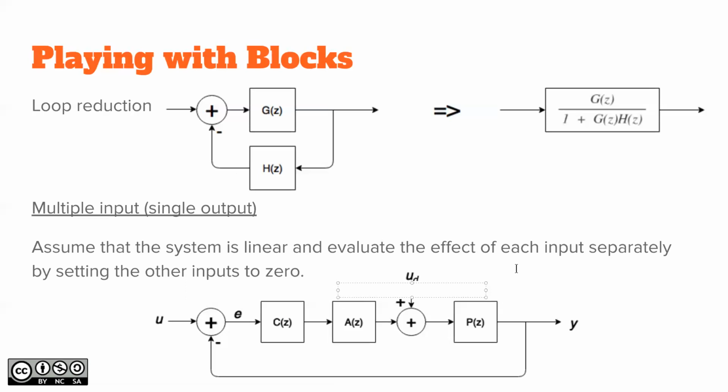Usually the control block is divided in two parts: the amplifier part and control. The control signal just gives some bounded values, for example between 1 and -1, to the amplifier. The amplifier is the real thing which has the transistors to drive the high current.